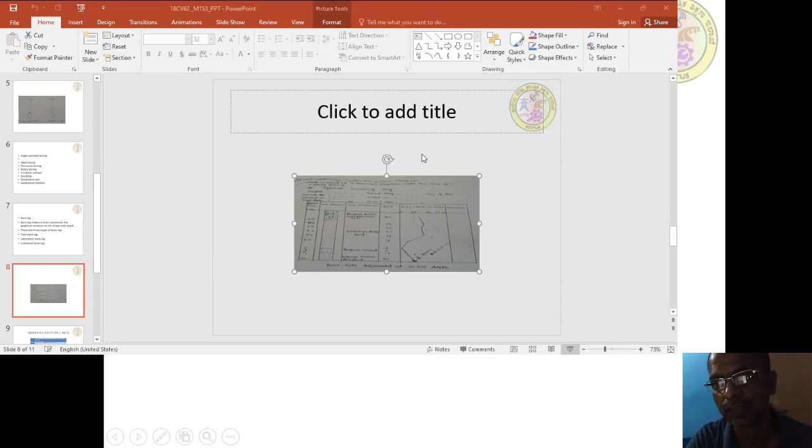They stopped at 10 meter, and if you plot it, when the SPT value increases the curve moves like this, and when it starts decreasing it moves in this direction. So this variation indicates the profile of how the strength and carrying capacity of soil vary with depth. This information is obtained by using a bore log, and if they stopped at 10 meter, it means the refusal strata is at 10 meter.